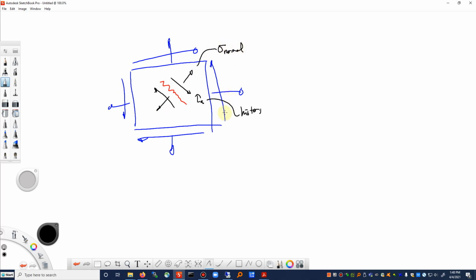Okay, and from a cracking perspective, that makes a lot of sense. If you're shearing and causing that initiation, and in addition have a tensile normal stress on that plane at the same time, then you can develop cracks more quickly and more readily on that plane, as opposed to another plane that didn't have the same high value of tensile normal stress.